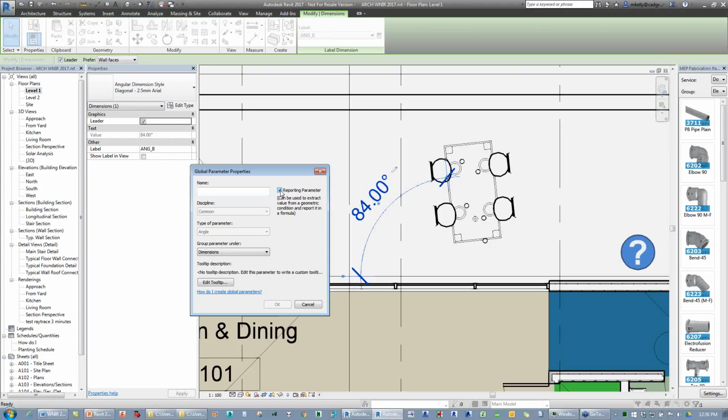So in instances where you want to actually get Revit to create a parameter that doesn't drive the geometry but just gives you a figure, which you can then use elsewhere, if you were to create two parameters that might actually work on the same geometry and push against each other, Revit will give you an error.